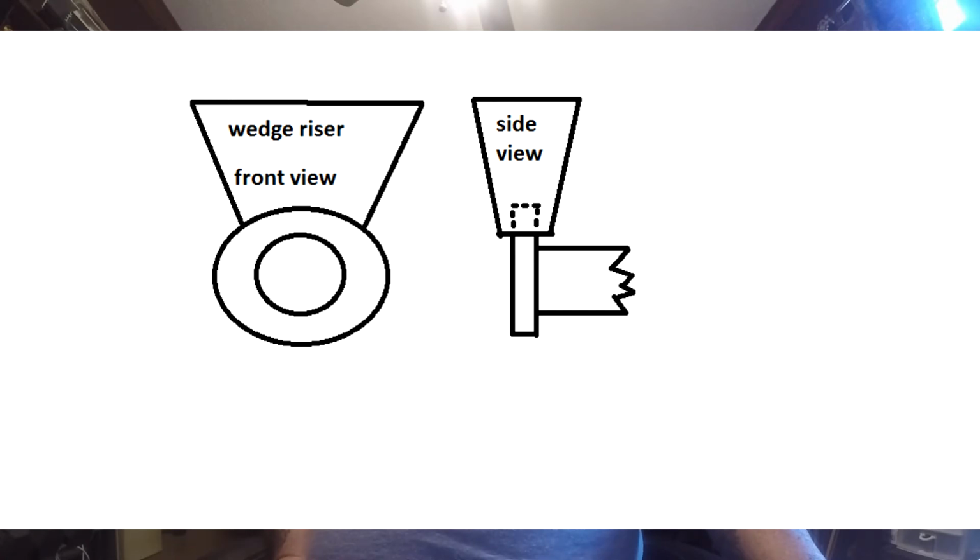And if you don't put a riser on that and gate into the riser, the top of that flange is going to be collapsed. Something like what you saw on that wheel, that one riser that was feeding the center hub of that wheel. Well, that'll happen in the flange, and if that happens, that means the strength and the shape of that flange will be affected.